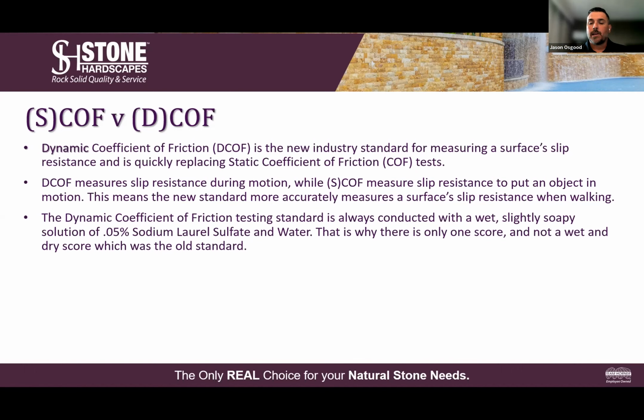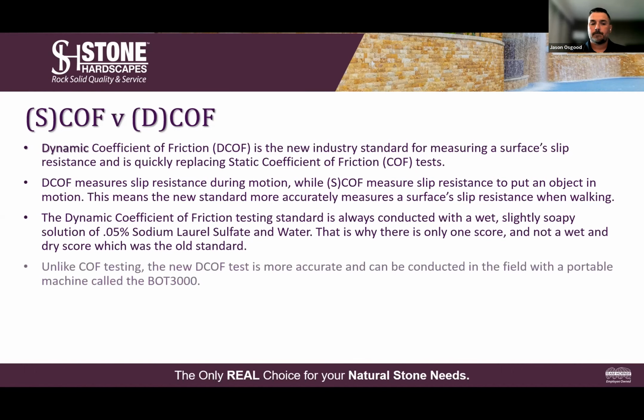With the dynamic, we only have one score now. And unlike the static coefficient of friction, the new DCOF is more accurate, and it can be conducted in the field with a portable machine called the BOT 3000. The standard coefficient of friction in our industry is 0.42.